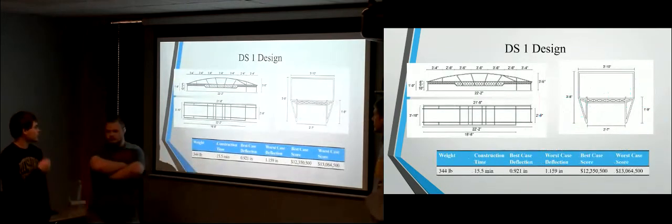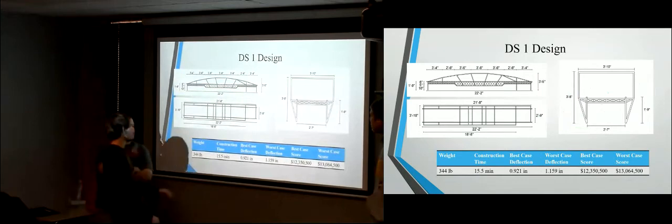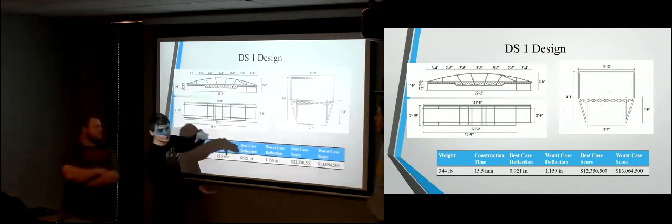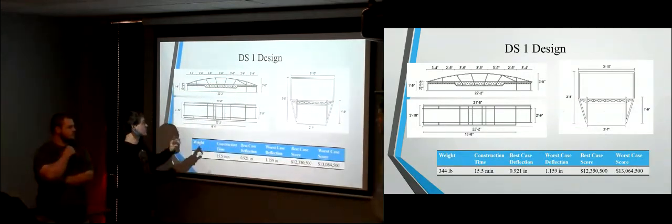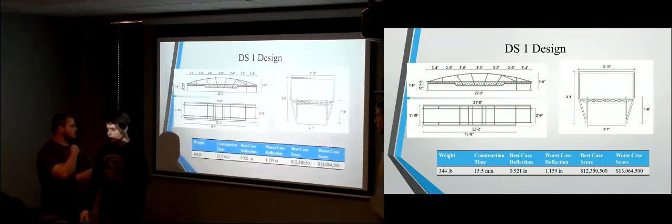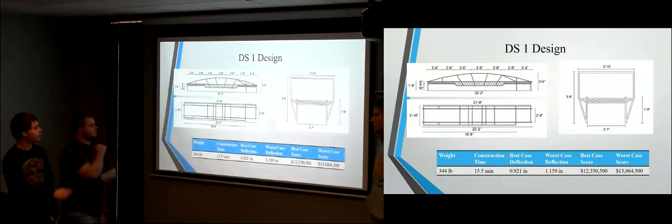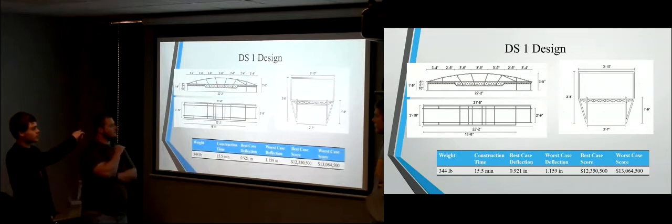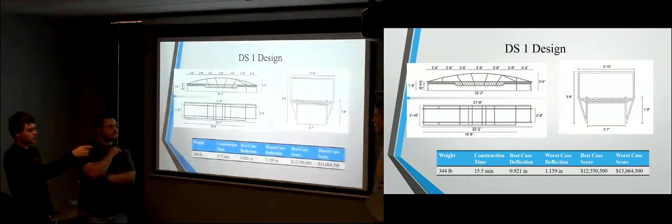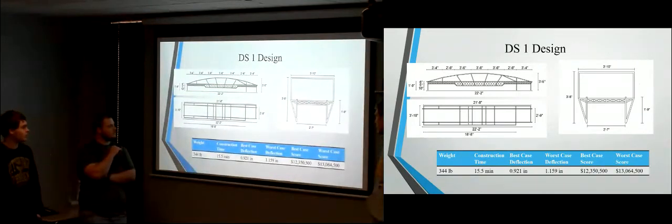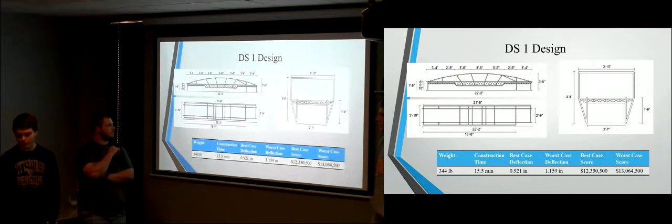And then this is mine. Like Adam said, it has that taper in the middle. Right here along the middle, there are actually 2 beams that would have to be connected to each other, and then at the ends, it's just one. Then the truss is just a simple arch shape. It connects to the legs on each end, so the truss is actually shorter on that side where it comes to that shorter span. And then there are just a few vertical members, and that's based on previous years' bridges that performed well.